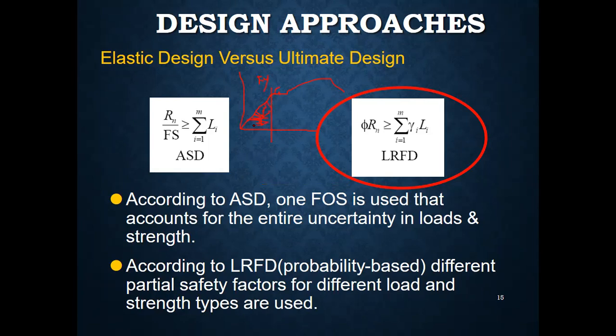But recent research states that steel members or ductile members do not fail at the yield stress, but instead keep on carrying the load till the ultimate stress. So the scientists are looking towards using the area of the strain hardening stage as well. The theory which uses this area as well is called the ultimate design theory.